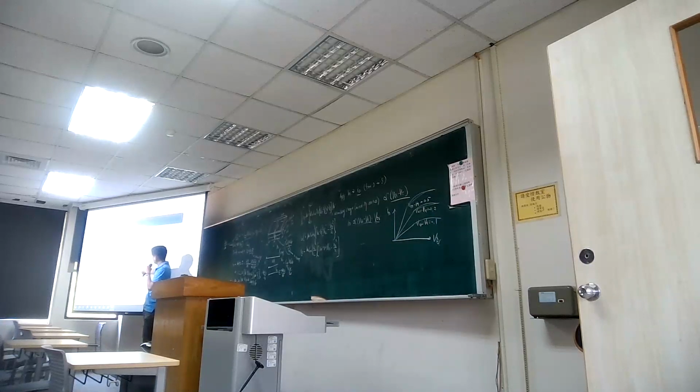So if you draw the curve for what we call the saturation region, the saturation current is independent of VDS. And VGS minus VT determines how much saturation current we can get. For instance, if you get a VGS much higher than VT, say VT plus 0.5 as VGS, that will give a lower current than VT plus 1 as VGS.